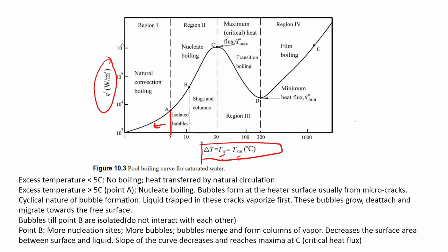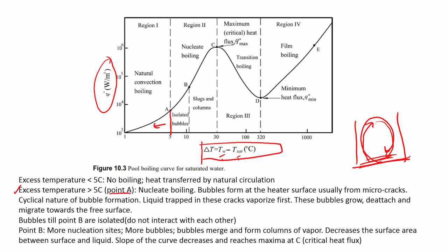So, it is like a problem in which you have a heated surface underneath. There is a circulation current that is created, because the layer of liquid near the surface gets heated, loses its density, climbs up, and then comes down once again, gets cooler. So, you get basically a recirculating stream, right. So, there is no boiling, but the heat is transferred solely by natural circulation.